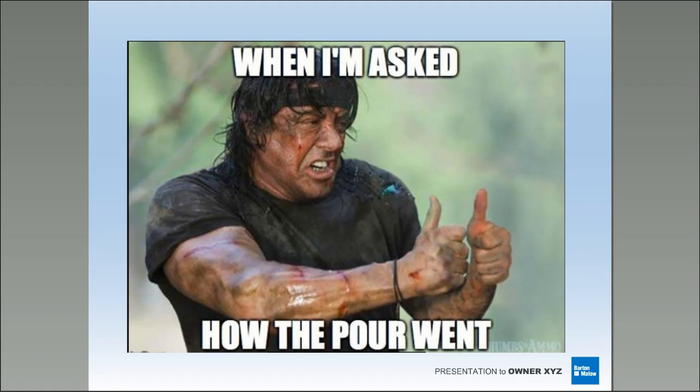I have polished both. There are some means and methods that your placement guy is going to want to do depending on what you're polishing that's really going to help you through that. I have polished some macro fiber slabs and have not had any problems with them. But again, it's got to be placed properly to be polished properly. All right. So it could be part of your placement problem. That's why you're having a problem polishing. I hope that helps.